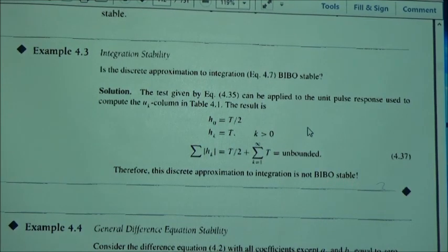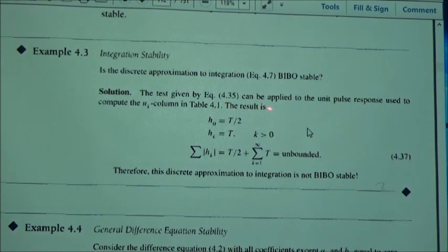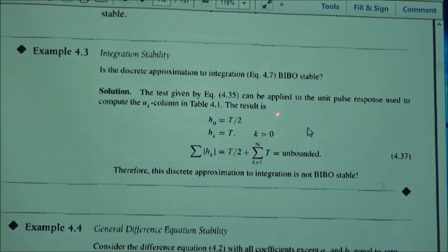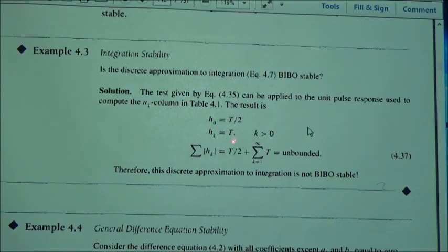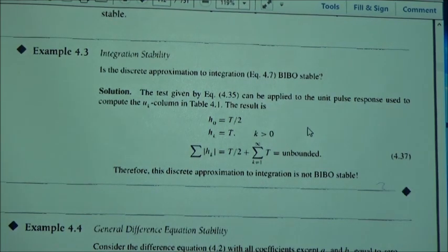On the other hand, if you look at the discrete equation of the trapezoidal rule and you move it into the Z domain and look at the poles, they are going to be outside the unit circle. That gives you the same conclusion. This is the brute force approach, which is hardly useful if the system is a third or fourth order system.